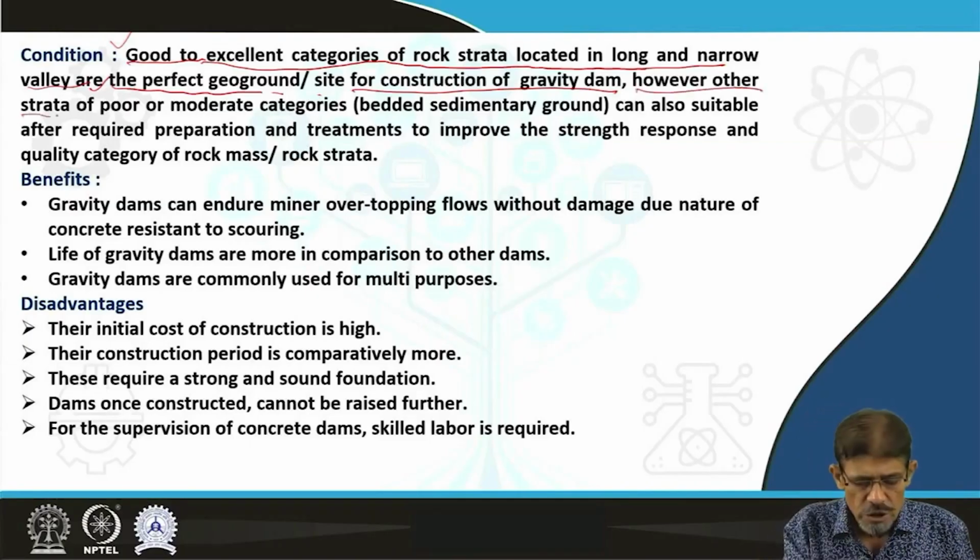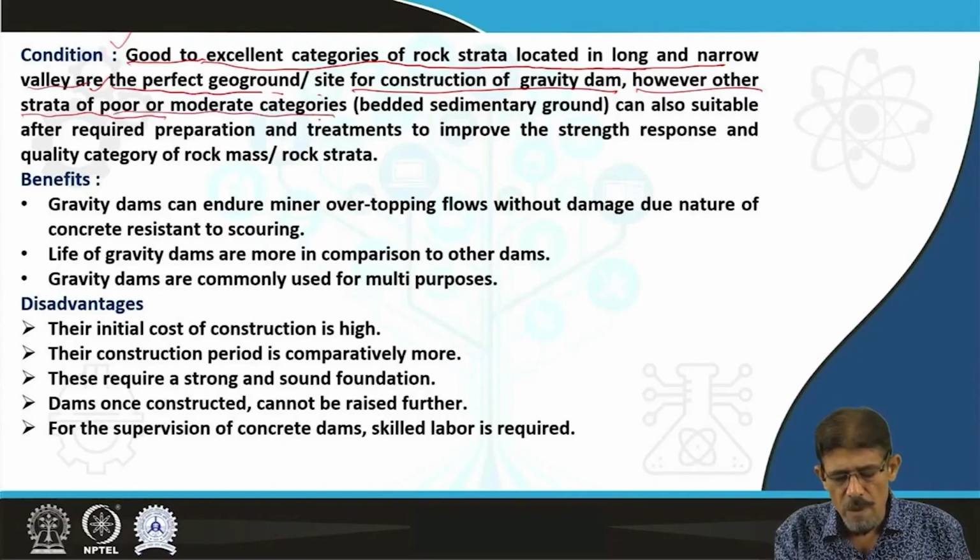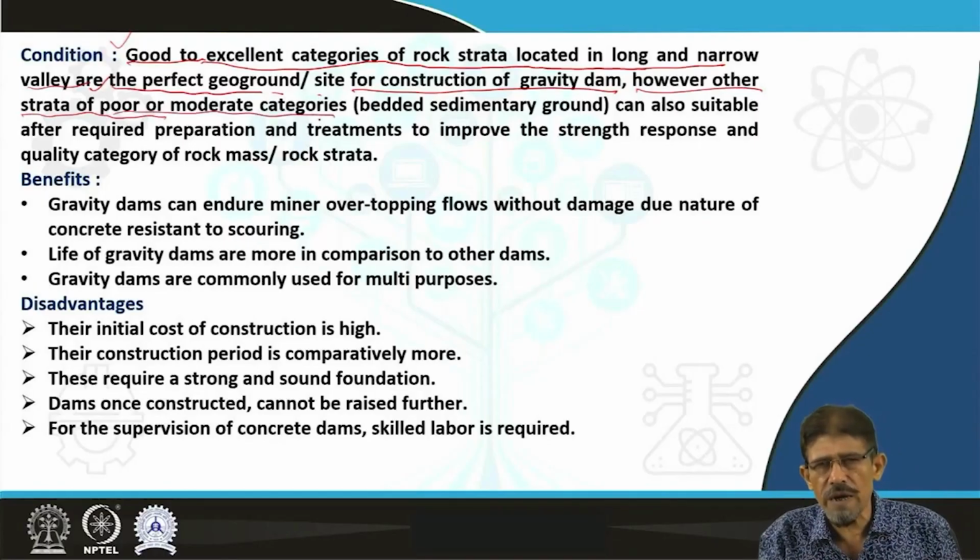However, strata of poor or moderate categories, like bedded sedimentary ground or layered igneous ground, can also be utilized if the valley is narrow, because if the valley is wider, then more material is required, which is not economical, is time taking and costly also.